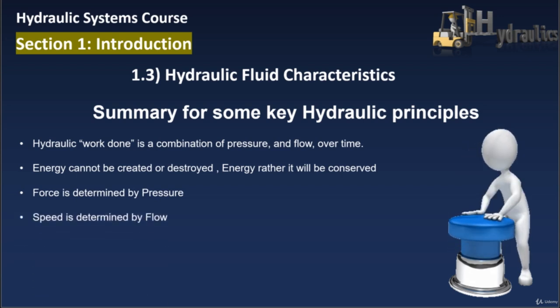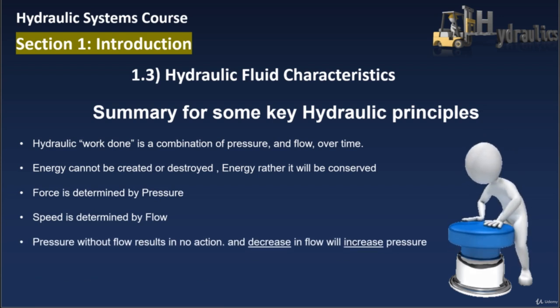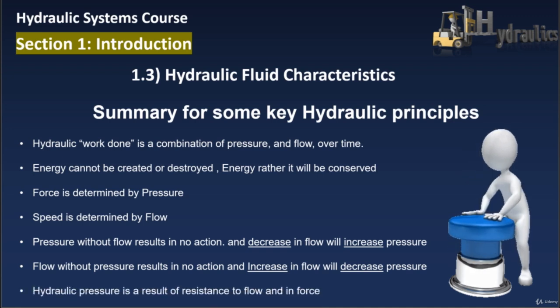Speed is determined by flow. Pressure without flow results in no action, and a decrease in flow will increase the pressure. Flow without pressure results in no action, and an increase in flow will decrease the pressure. Hydraulic pressure is the result of resistance to flow and force.